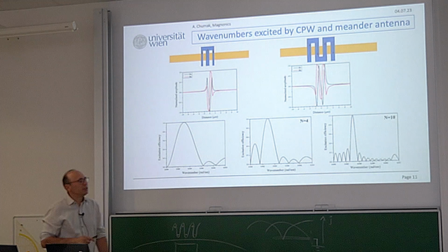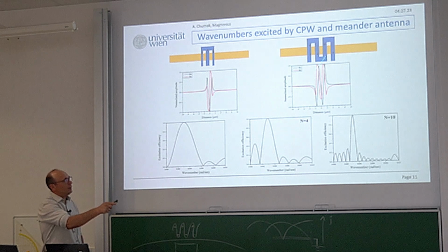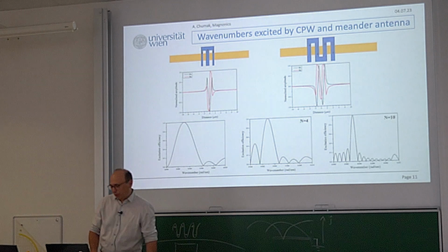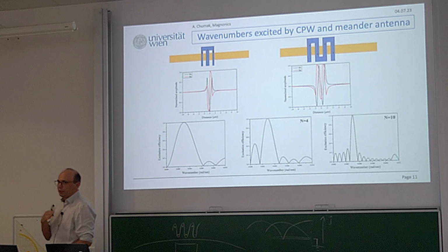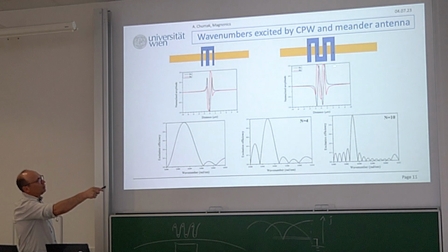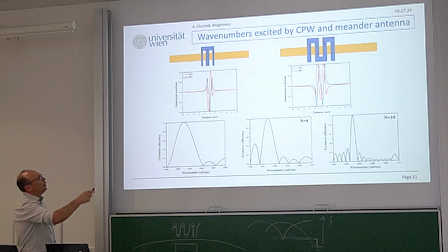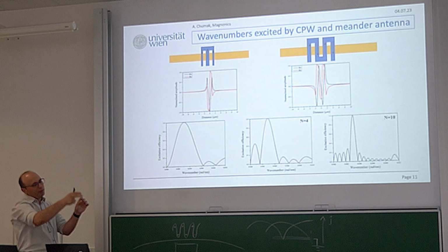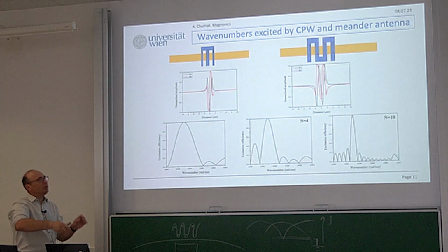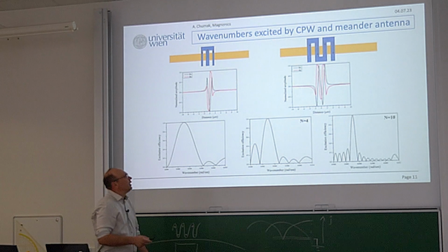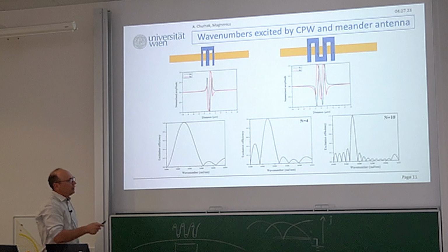There are different designs I do not discuss, because when you make this antenna, you also still have to think about characteristic impedance, how to send microwave signals so that they go through the structure. Therefore, pretty often people put such a ground here. Additionally, or people take this CPW, which is 50 ohm matched, and then all three wires bend in order to have 50 ohm matched, but meander.